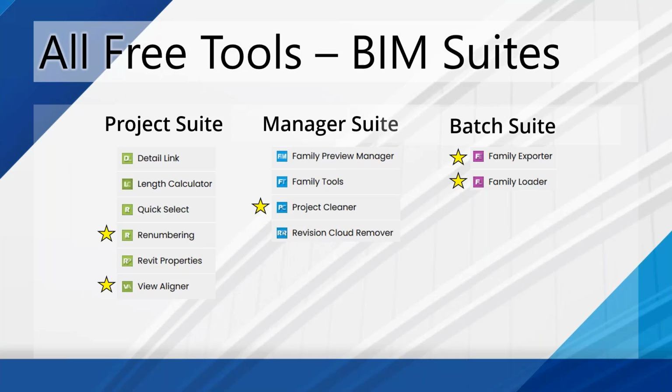You can filter and create selections based off existing filters in Revit, categories, and nailed down to the parameter and the parameter value. So you can really get creative and put together something that selects everything that has a 1 hour rating in your project. So that's walls, that's doors, that could be ceilings, windows, floors, a bunch of different things, and various wall types and various door types, right? You can select all of that in one shot, and then you can save it and use it on a different project.